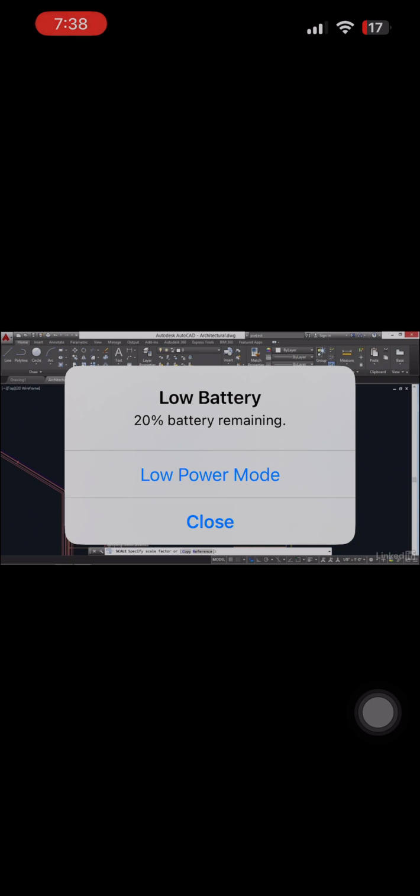So if I wanted to scale it graphically, I can just carefully move the cursor a little bit and click a point. And that will set a scale factor graphically. But that's not really what I want. Let's undo and try this again using a scale factor as a number. So let's scale that again.